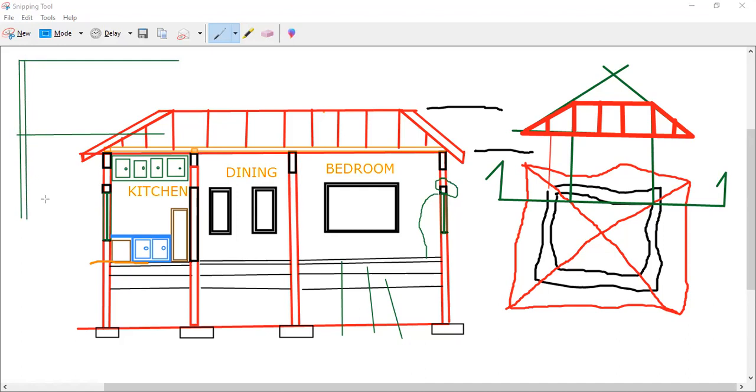You get that? For offset, you type O, enter, then click Through or type T on the command bar, enter. What Through does is allow you to click, move, enter distance, click, move, enter distance. So you go really, really fast. I'll click the last line, move, type the distance, get this line. Left click, move, enter 150 or 170, whatever the case may be. Click, move, enter the distance for the dining, and we go across until we get all of those. So this is basically how you start this.